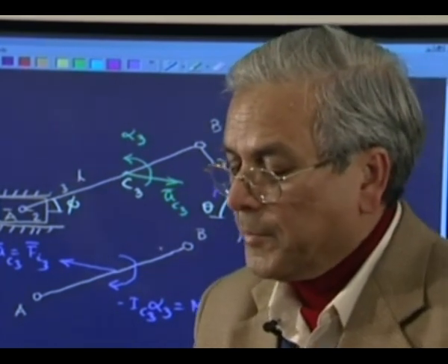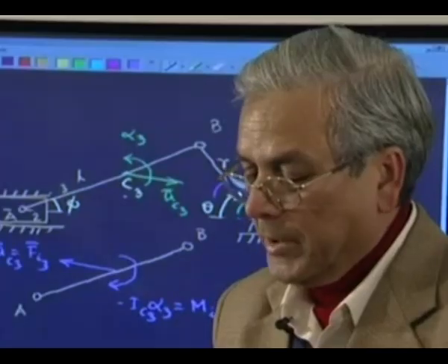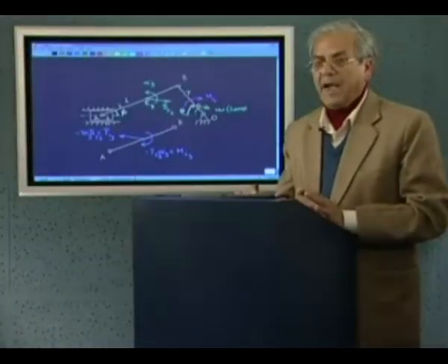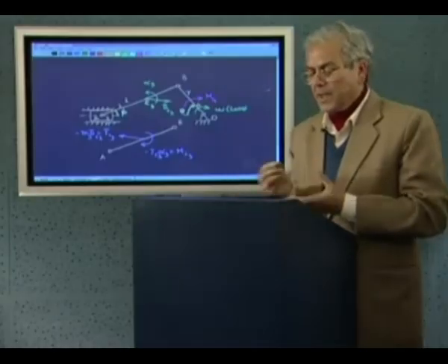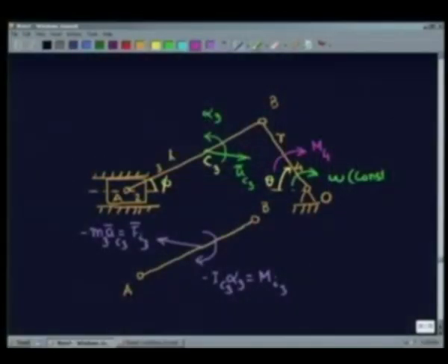Now we know that this and these ends will be subjected to link forces. You can also give some idea that there is some external force acting on this, maybe the weight of this. But to keep the problem less complicated, we don't add any external force, which could be easily done. But we know that there is some force acting here, which is a reaction force here from link 4 to link 3, and a reaction force from here, which is from link 2 to link 3.